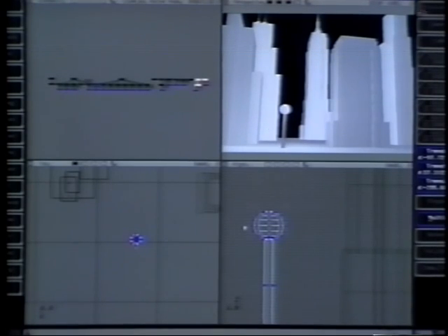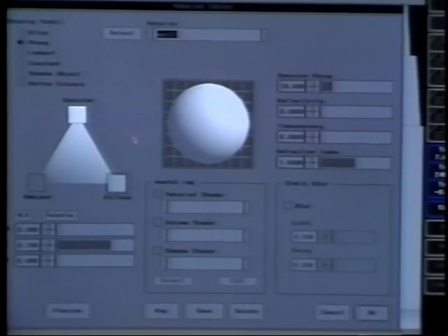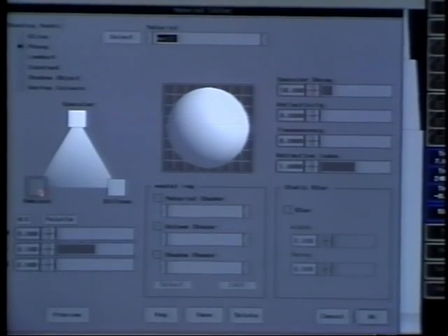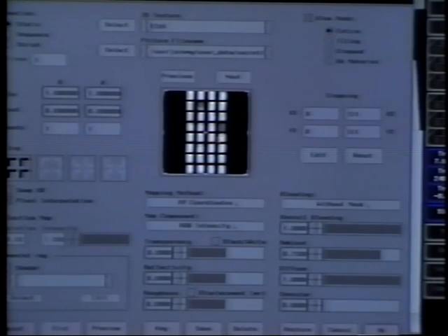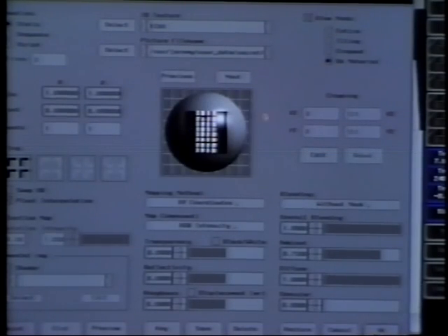What we do is first make sure that the material doesn't have any ambient value, and we should do this for all the materials in the scene that don't have their own illumination. Now in 2D textures, we can load up the map of the lights for the building. Now to just map the luminosity of the windows onto the building, we want this map to only affect the ambient or self-illuminating part of the model.